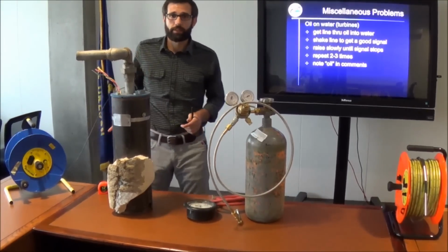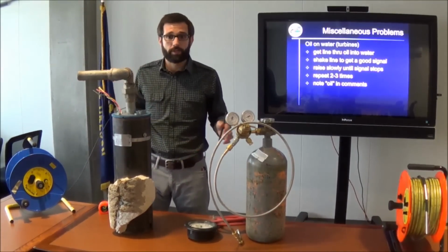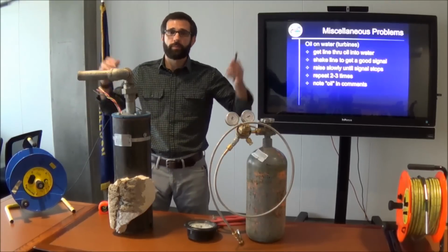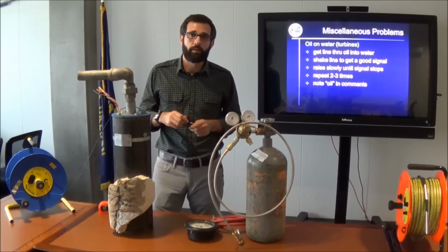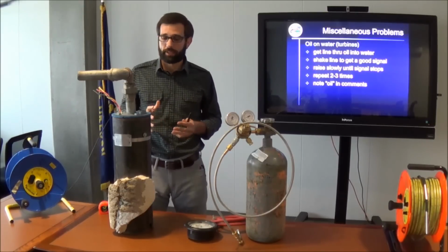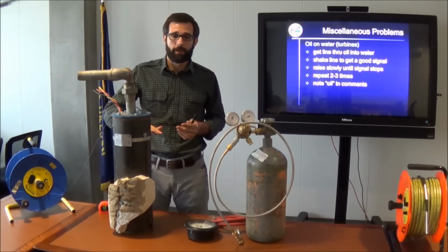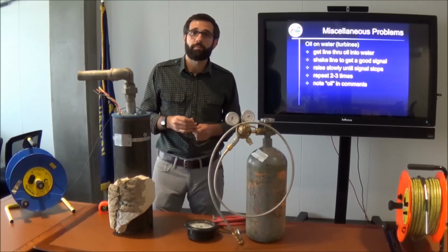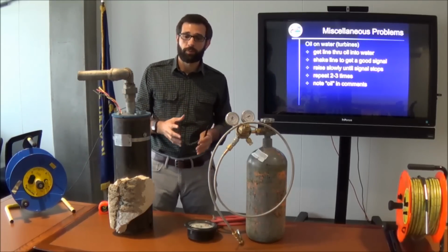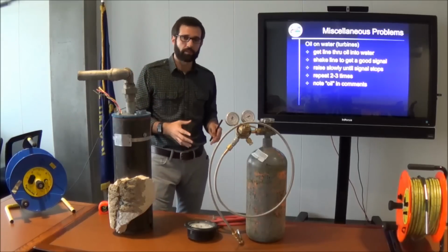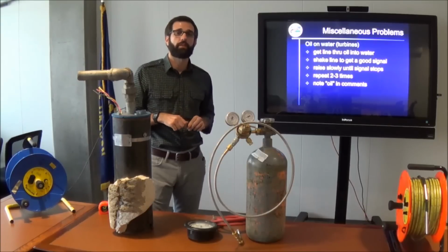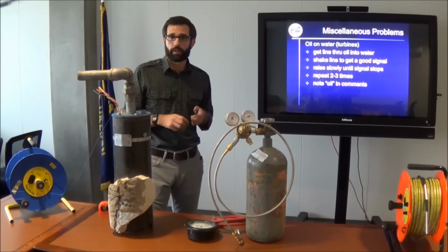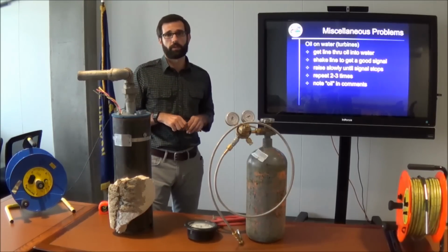Another problem is oil on the water. If you're out measuring a large irrigation well and there's a big turbine pump sitting on top of the well, those are typically lubricated with oil, and sometimes a lot of oil can get on top of the water level in the well. As you're sending your tape down the well, it can get coated with oil, and the coating doesn't come off until you could be several feet into water before you get your signal back. And if you're going through it a bunch of times, you could stir that oil-water interface up, and that also causes problems.